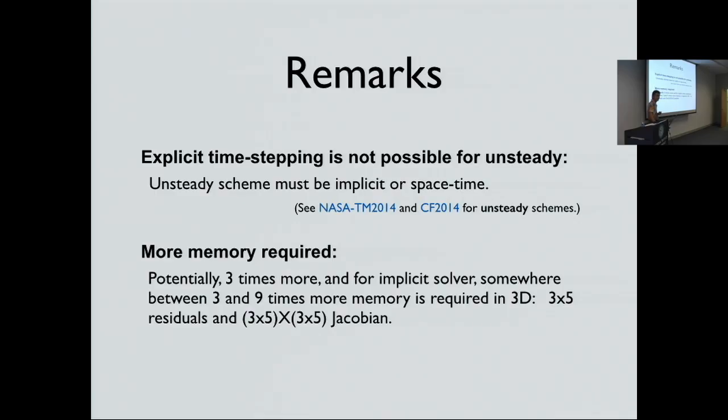When you're doing turbulent problems, what do you anticipate would be the impact of doing this upwinding for viscous terms? In terms of dissipation and things like that. Because it's making it kind of anisotropic in some sense, right? Whereas the traditional approach has been to do upwinding in the convective part, but the diffusion part itself is more like diffusing. Oh yes.